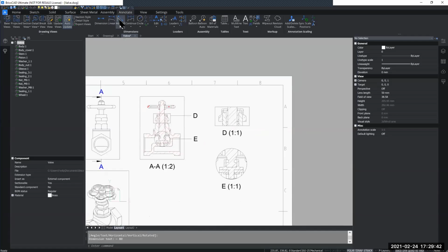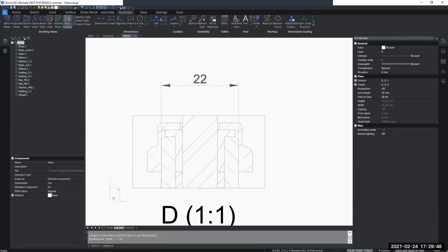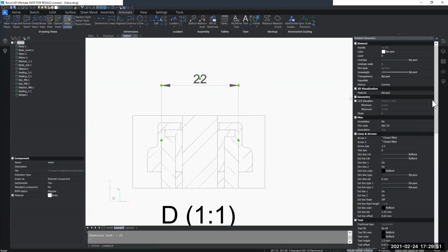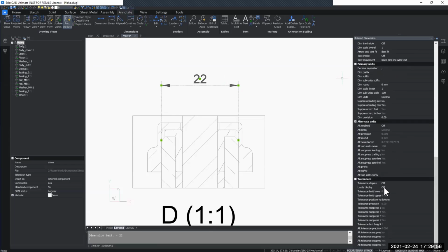You could also apply some different fitting sizes. Now this next part is not in the handout, but if you select a measurement and scroll all the way down, you can see tolerances here. So you can then choose to display a tolerance. So for example, here, you maybe want to have a tolerance of plus minus 0.5 or so, minus 0.5 plus 0.1, for example. And so you can change these settings down here.